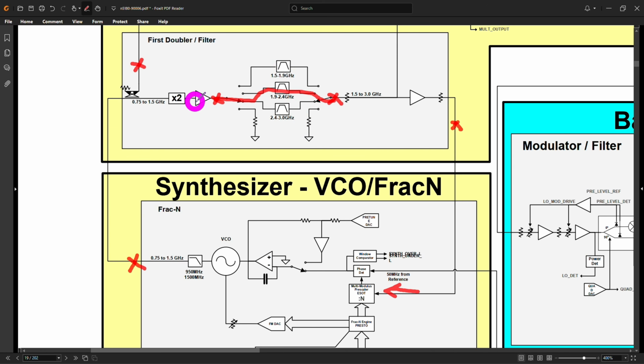Now, it's more than just the fact that maybe one of these filter banks is broken or the switch is broken, because there's also a dynamic characteristic. When you switch from one filter bank to another, there's a brief moment when the loop is open, and this whole instrument, perhaps using the pre-tune and every other thing in here, has to calibrate and coordinate that so that the synthesizer comes back online as quickly as possible and retains the lock. So from an end user point of view, it looks continuous, but it's actually not internally continuous.